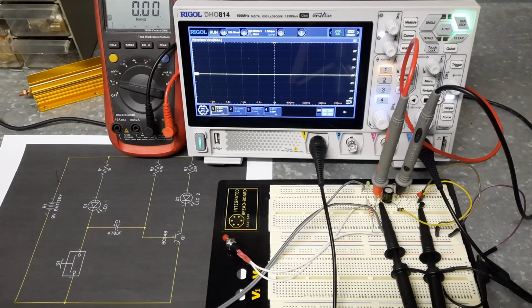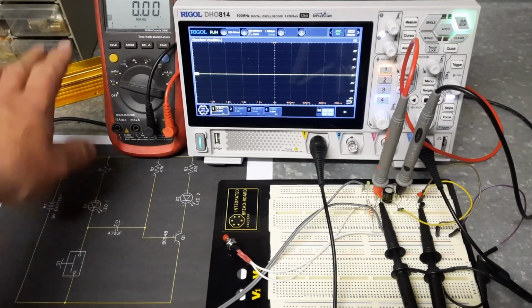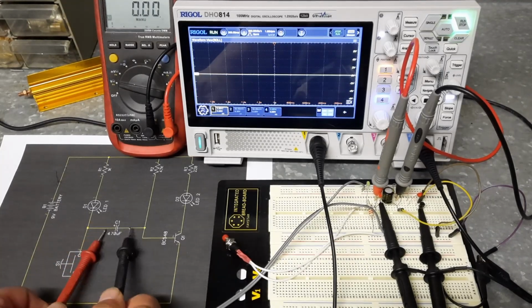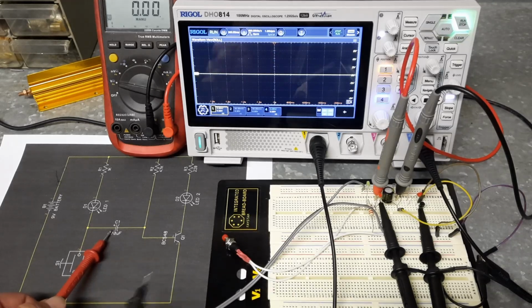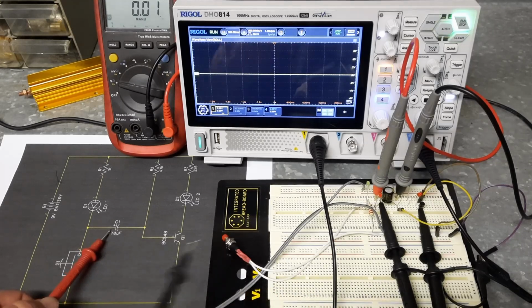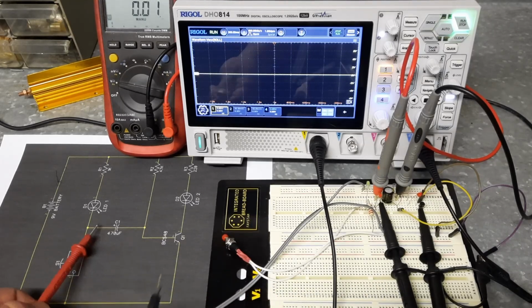But what I've also done is I've placed my voltmeter on DC, and I've put the probes across this cap. So they're directly across it. I can't put my scope across it because I don't have a differential probe. And if I try to connect the negative or the ground of the scope here, it'll short out with everything else that's connected to the ground of the scope.